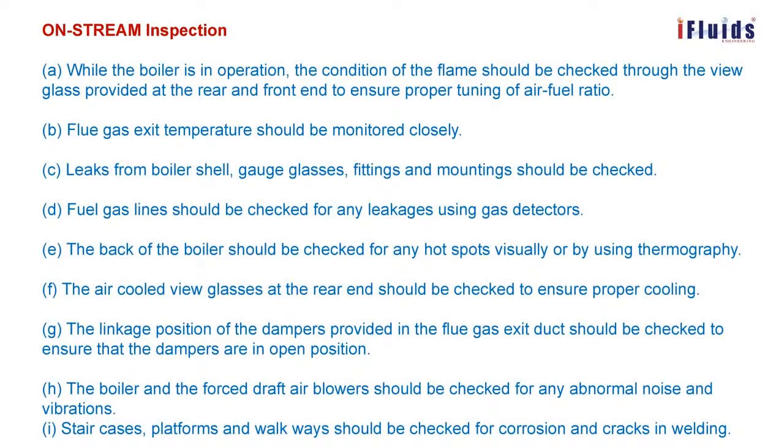The on-stream inspection is while the boiler is in operation. The condition of the flame should be checked through the view glass. Flue gas exit temperature should be monitored closely. Leaks from boiler gauge glass fittings and mounting shall be checked. Fuel gas line should be checked for any leakage using gas detectors. The back of the boiler should be checked for any hot spot visually or by using thermography.